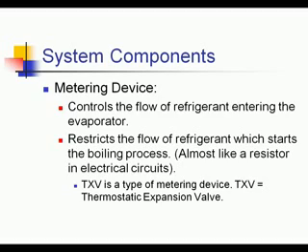Then we're first dropping our sensible heat. Remember, sensible heat is the basic measurable heat. We drop from 200 to 125 almost in the first row of the condenser. We continue at 125 all the way almost through the condenser.